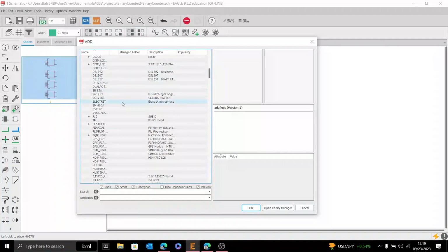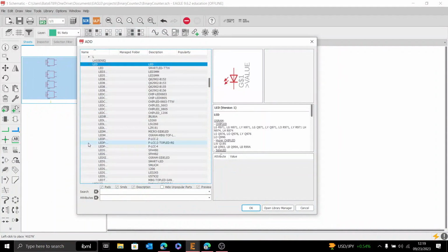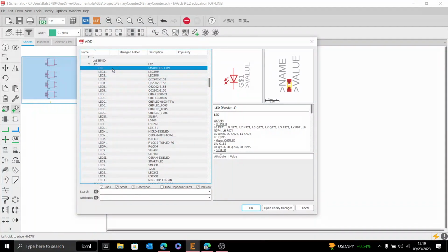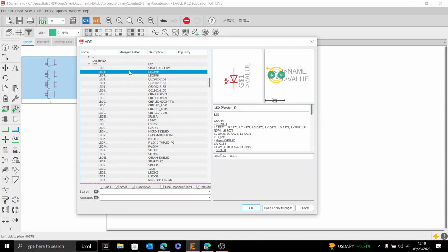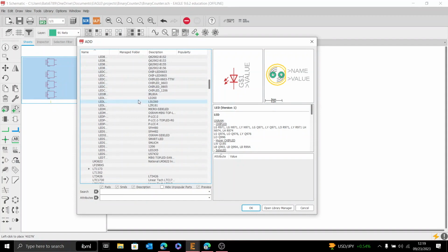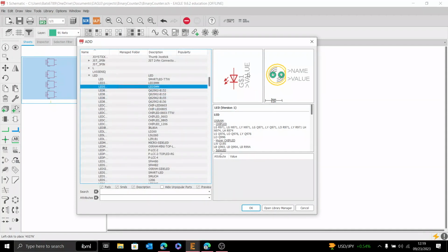LED. And there we go. So this first LED here you can see is a surface mount. I don't see the chip package right off. I'm going to use through-hole LEDs, 1 because it'll be easier to solder, and 2 because I think they look a little cooler than the surface mount LEDs. But that's my opinion. Let's go with, I'm feeling the 5mm today.